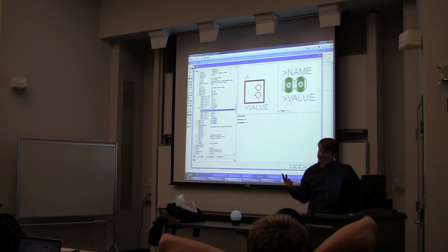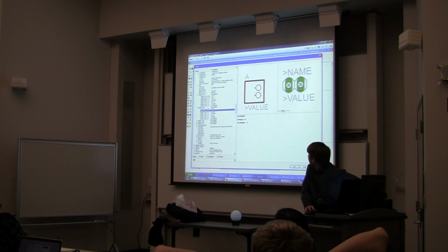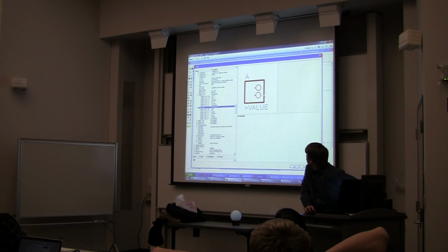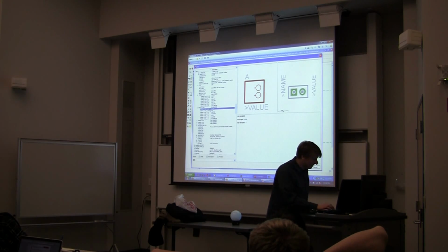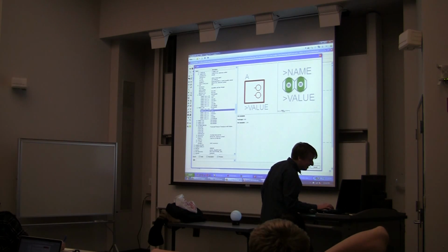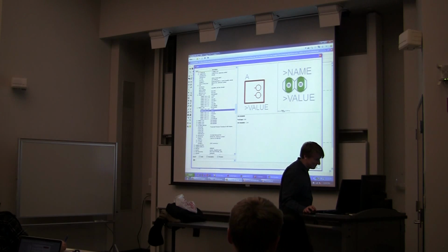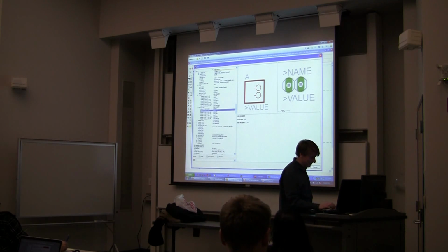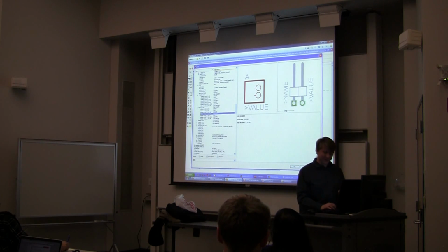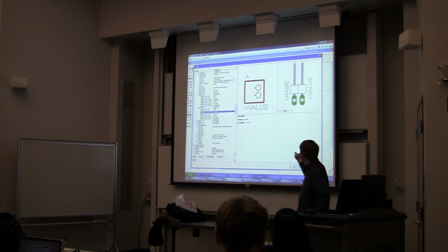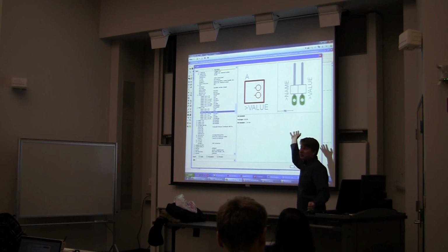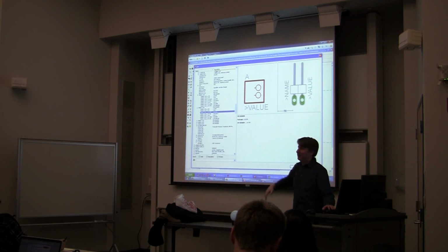So what does it do? It has two legs. And I'm just going to solder it down to my board. So I'm going to use this pin header 1x2 because I want two legs. And then I got all these choices. I've got 2 millimeter metric. I've got 0.1 inch. I've got all kinds of crazy options. Here are some 90-degree ones, which if you look at them, they don't really change the size of the holes. They just put prettier pictures on your board to remind you that you're going to have this right angle header.